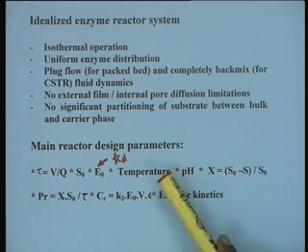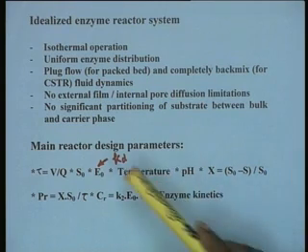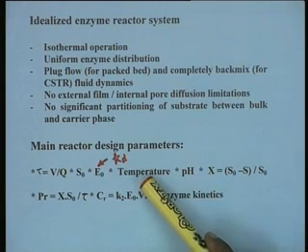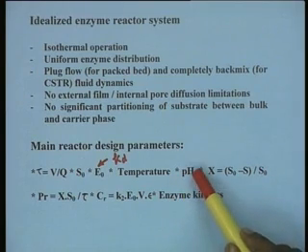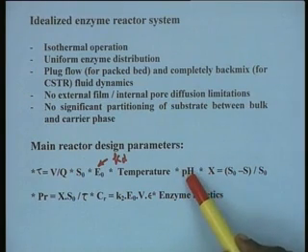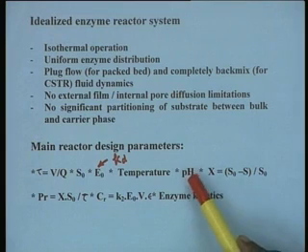Then the temperature of operation, because deactivation also will depend on the operational temperature, and I would like to mention here that most continuous enzyme reactors are usually operated a little below their optimum temperatures, just to reduce the Kd value and increase the operational half life. Then pH, of course pH here is not only monitoring, but more important is the control of pH. How are you exercising control of pH?